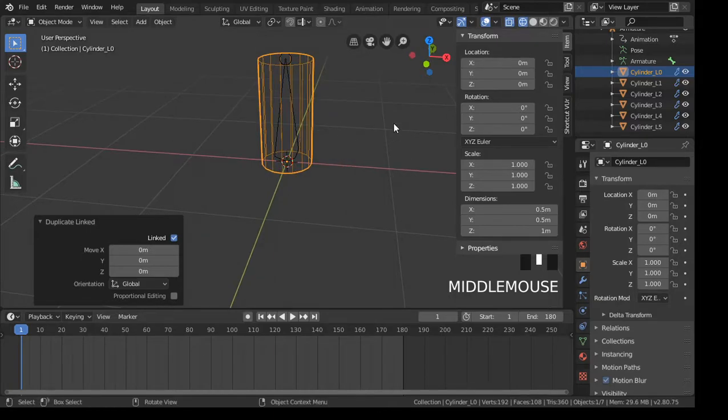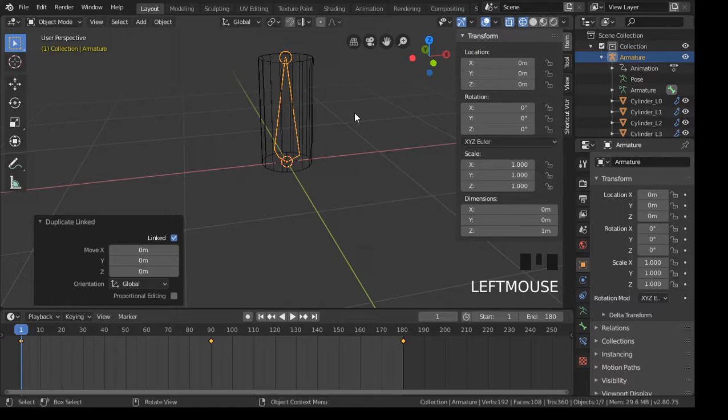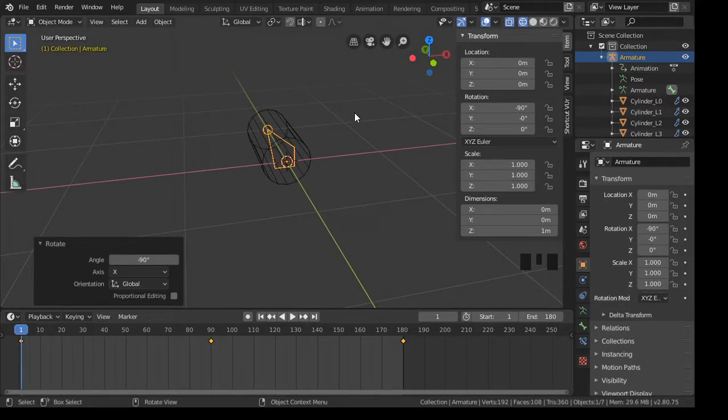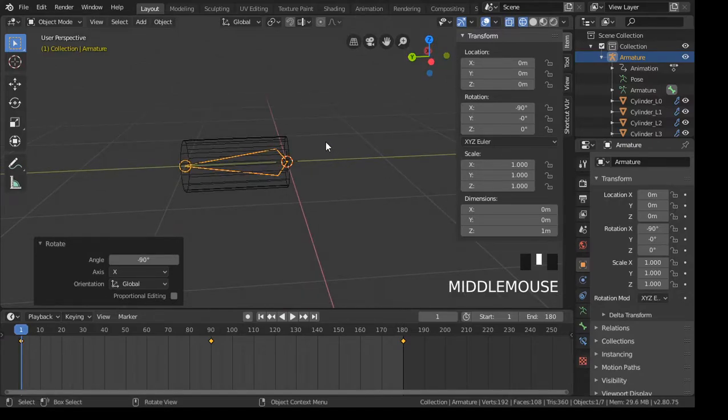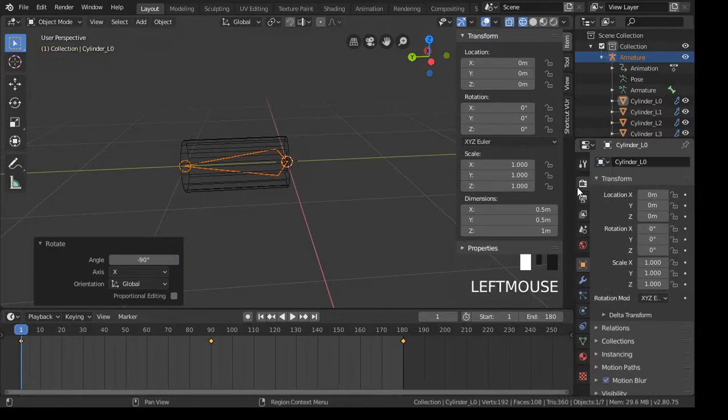So, to get the object to animate correctly in TMTK, and I should say work, because if you don't do this then it won't work, you want to select the armature itself and push R, then X, and then -90. As you can see, the mesh followed, and that's fine, because if you go over to this, you see the armature has a rotation on X of -90, but when you select the mesh itself, see how it's zeroed out? That's what you want.